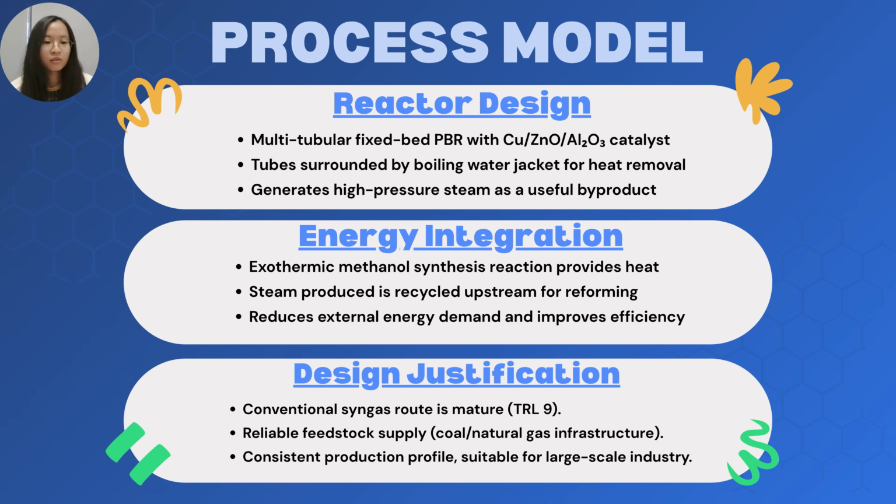For the reactor design, we chose to use a multi-tubular fixed bed PBR with copper, zinc oxide, aluminum oxide catalyst. The tubes are surrounded by a boiling water jacket for heat removal, and it will generate high pressure steam as a useful byproduct. Moving on to the energy integration, methanol synthesis is an exothermic reaction which will provide heat.